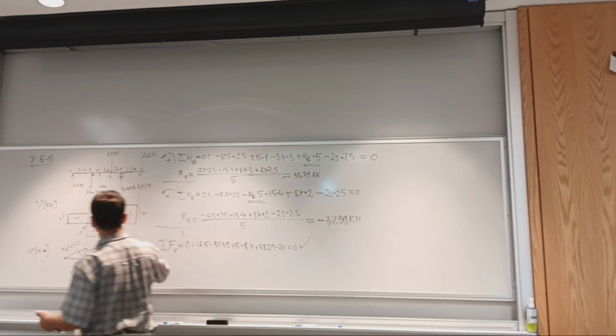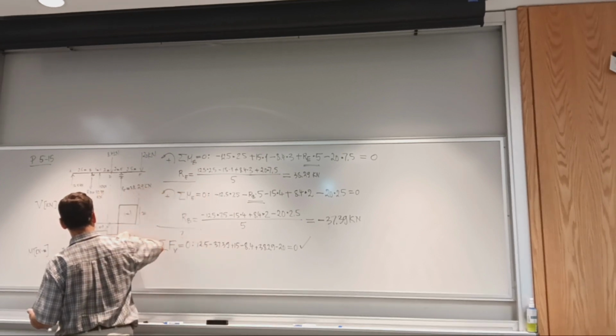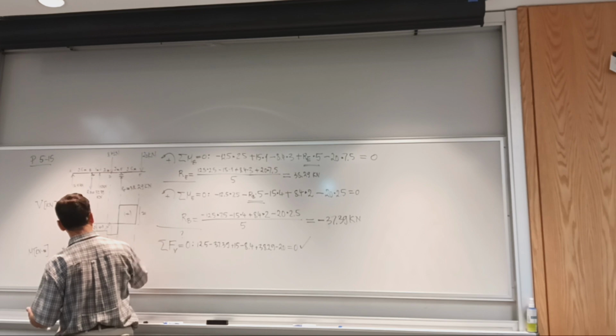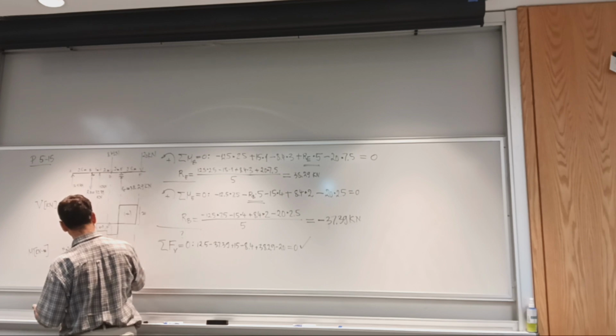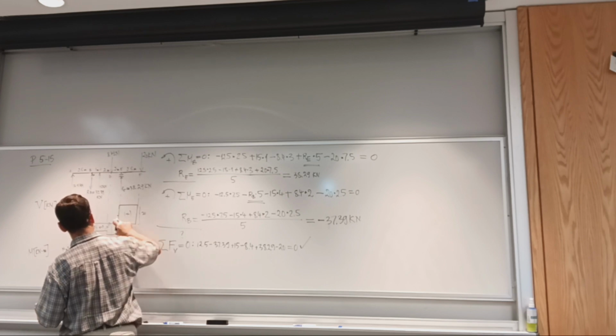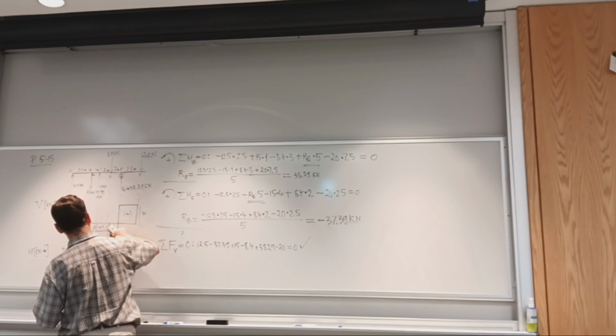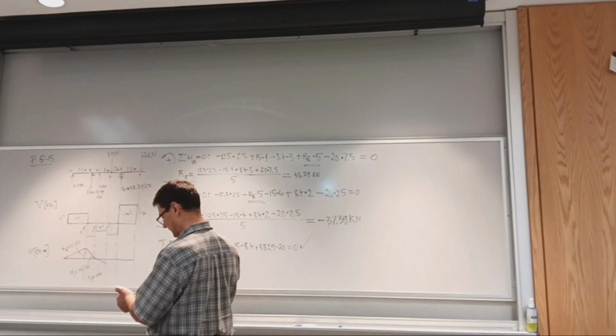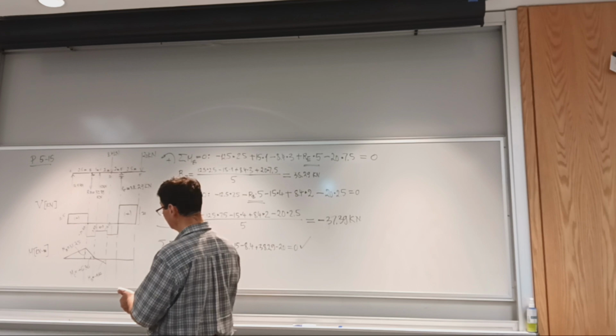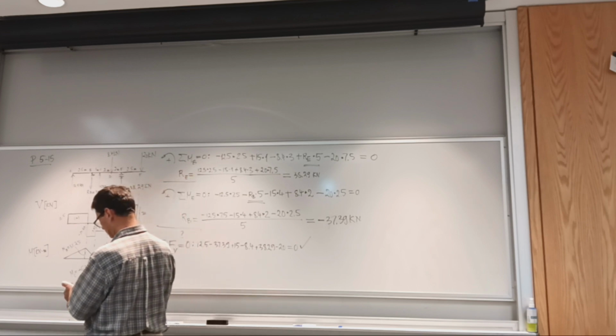Okay. I continue with a negative slope that has increased to negative 18.29. Let's see what the moment at E is. So I have the last moment calculated, and I'm going to subtract further, that is, add a negative area, which is 18.29. So I say negative 18.29 times 2.